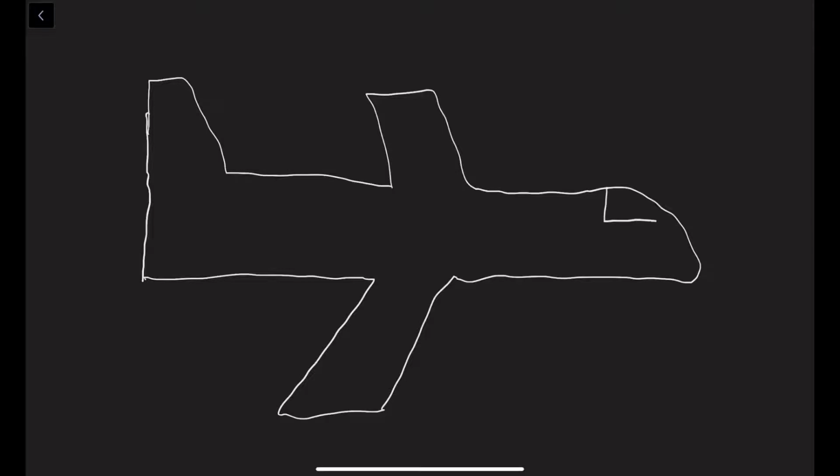If there was a fault in any of those wires, finding it manually by searching the airplane simply wouldn't be feasible, given the volume of wires and the difficulty of dismantling the airplane to search for it. By using a TDR, we could measure the exact place that fault is at. If it was here, we'd be able to pinpoint that location and go in and directly fix it. So now let's take a look at a couple of examples.